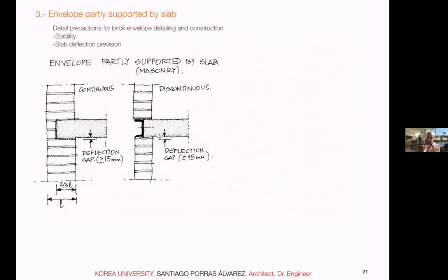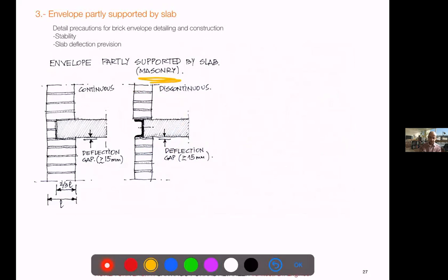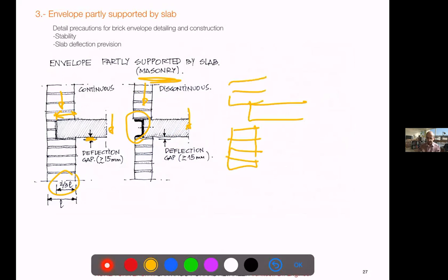One thing you have to be careful about when you work with masonry especially is to support at least two thirds of the masonry, so the center of gravity is well supported and it will not fall, or to have a structural element, and always leave a gap, because the slabs always have some deflection. We know by structural studies that it will move, and usually it is carrying a lot of weight. So when you have the slab, we put in the bricks, we put the following floor's bricks, the two thirds, and we leave a small gap.